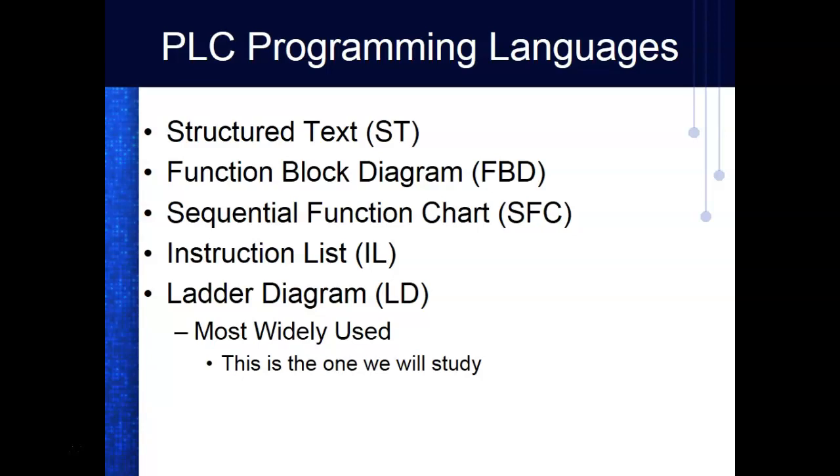What they're trying to do is make a path where if you didn't come up through the electrical trade and you don't understand relay logic, you still have the ability to write programs for the PLC. Your programming application determines which languages are available for you to write programs in. So RSLogix 500, the one we're using, only supports ladder. And if you learn ladder, you'll be okay, because every PLC that I know of supports this language.